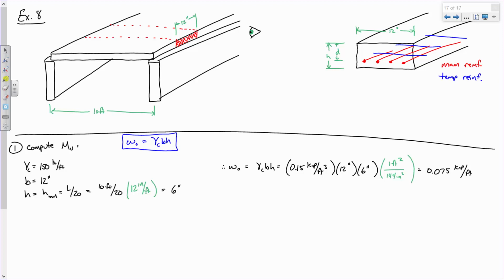And so if this dimension is like, I don't know, 16 foot, you'd say that the live load is 200 PSF times 16 foot, right? Remember, you don't multiply by the length because you use the length to say WL squared over 8 to get your moments. But what you're doing is taking that distributed, or pressure load, and collapsing it into a single line load on that beam. Does that make sense? So you would take the pressure load times the tributary width for that beam. Does that make sense?